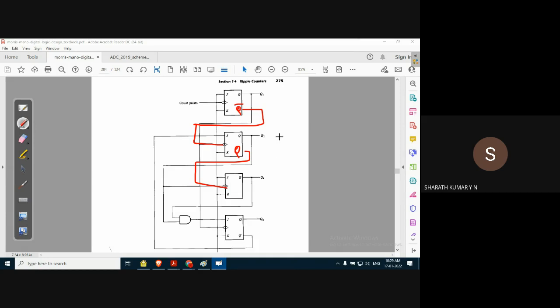So it starts from 1001 initially. Of course, when the counter is started, it will not start from 1001. It will start from zero initially. Initially it is 0000 when the circuit is turned on, so the next count will be 1001, which acts as the initial state for the BCD ripple down counter. Because the complement output is applied as a clock pulse to the next stage, at this stage the complement output should be given as an input to the AND gate.